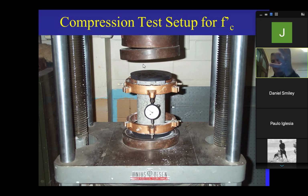And then look at the head. It swivels. It swivels, and then the rubber piece. Why? Because we want to minimize the eccentricity. We don't want this machine to push on this cylinder at the corner. No, we want it to adjust to itself over that rubber, so it can minimize the eccentricity. All right.